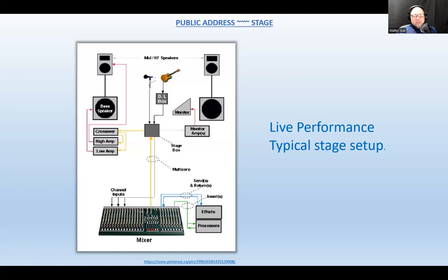But it's going to have some resistance because that's the natural way of things. Cables do have resistance. The longer they are, the more resistance a cable is going to have. So 1 or 2 ohms compared to 300 ohms or 600 ohms is going to be quite insignificant. However, if we have high power speakers, it could be 4 ohm speakers, then the resistance of that cable compared to the input impedance of that speaker would be comparable.